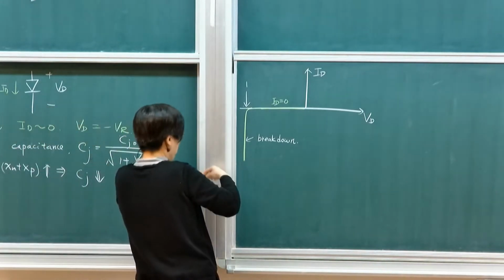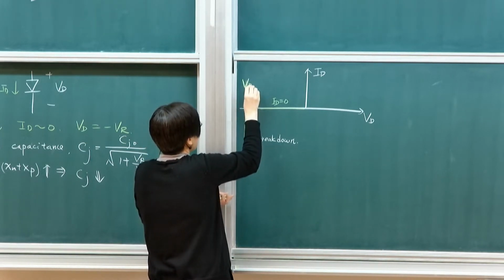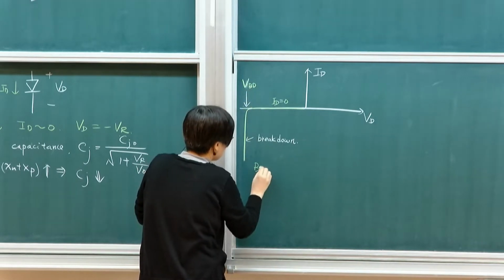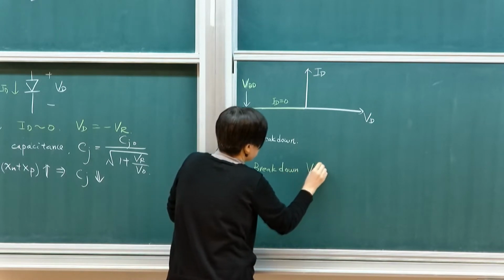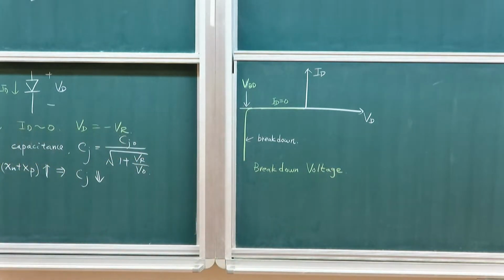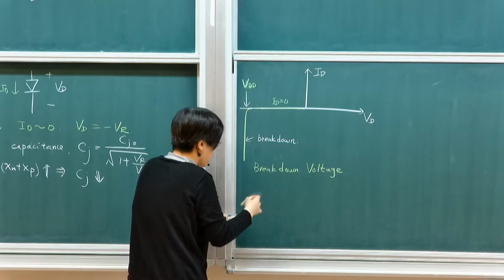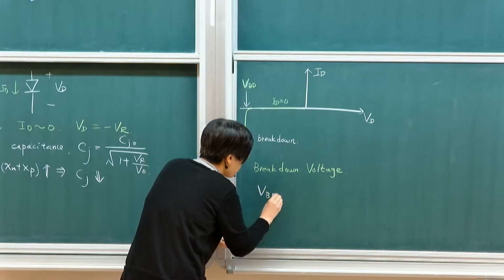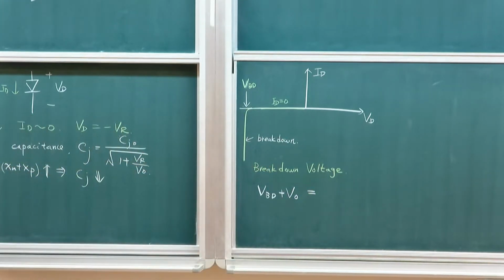So you want to know the base. Our key parameter in this region is what we call the breakdown voltage. Your breakdown voltage, if you think about it, is this voltage VR, so it's V0, so VBD. What happens at VBD is that your breakdown voltage plus V0 will then give you the maximum triangle area. So what limits the maximum triangle?